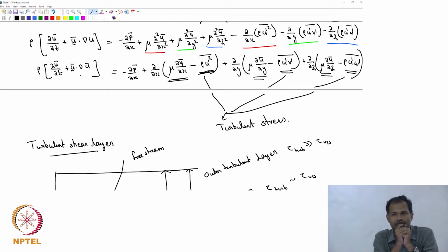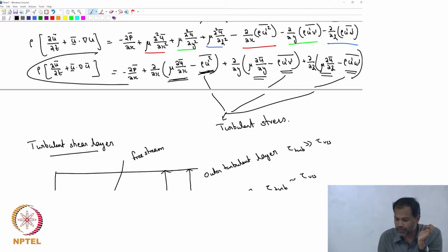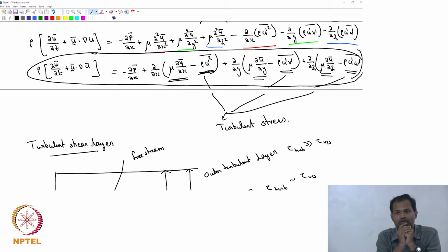Right, that was the governing equation. If I am solving for the wall layer or viscous layer, in this equation, what all terms can I put to 0? I can put this to 0, that to 0, and that to 0, and then try solving it, because I know that turbulent stresses will be small, and therefore you are going to get some velocity profile, right.